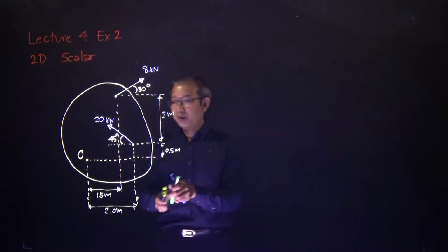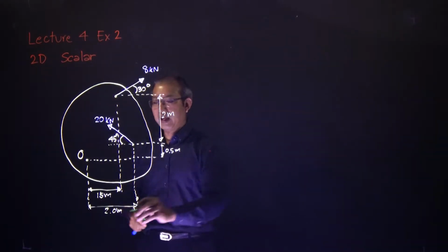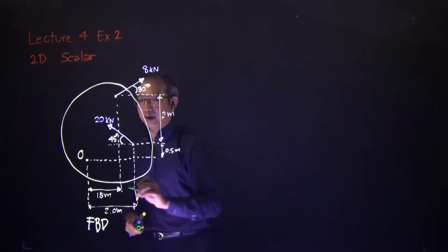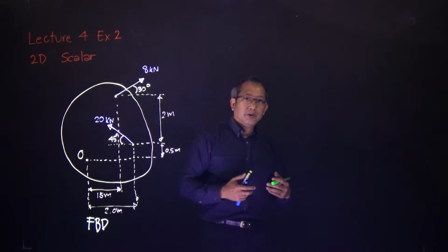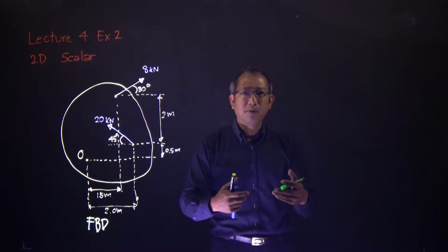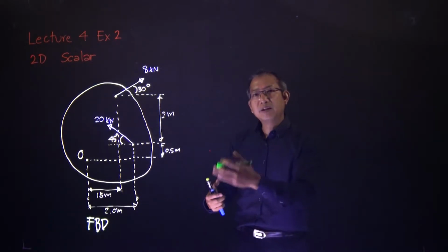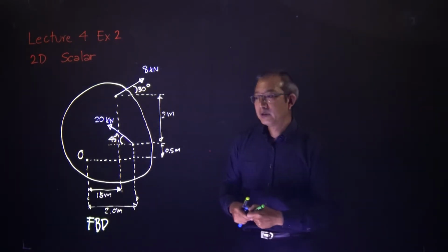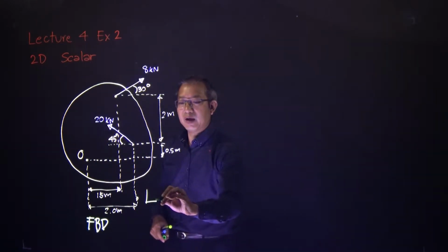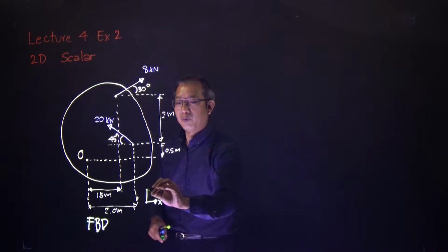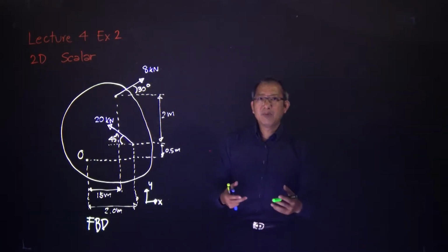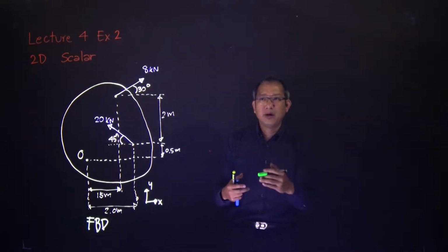Just to make sure we understand the same thing, this is a free body diagram already, right? Now, to make our life easier and so that we can communicate on the same level, we'll designate what is x and what is y so that we can talk about the same thing. In this case, I will have x to the right hand side positive and y up and down, whereas up is positive. With the scalar method, we solve with one axis to another.